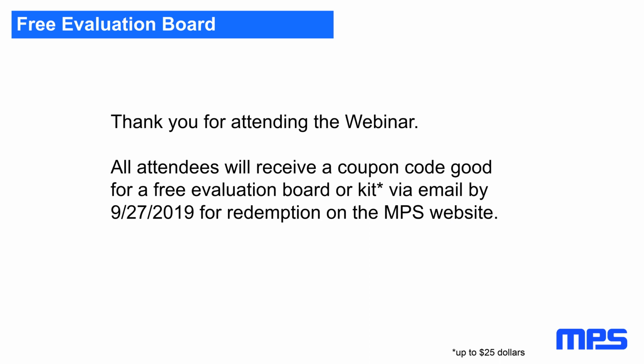So I would say up to 50, 100 megahertz, it doesn't make too much difference, even if you slow down your edges. It's another issue if you are talking about really high voltages like offline power supplies. There you go to lower switching frequencies and you try to make your edges as slow as possible. But as long as you run 400 kilohertz or above, or 2 megahertz, there's not too much you can do. The slopes are in the range of a nanosecond, 2 nanoseconds, 3 nanoseconds, but you can't make a 10 nanosecond slope on a 100 nanosecond on time. You would waste about 20% of efficiency and create heat for it.